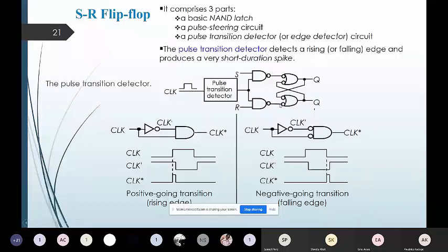Let's check for this bubbled OR gate output and how they are going to generate the outputs. So in this case, what we are observing is that if the 0 output of the upper NAND gate is produced when the S input is 1 and the clock is a positive clock, this 0 will be bubbled at the input side, so it will get 1.